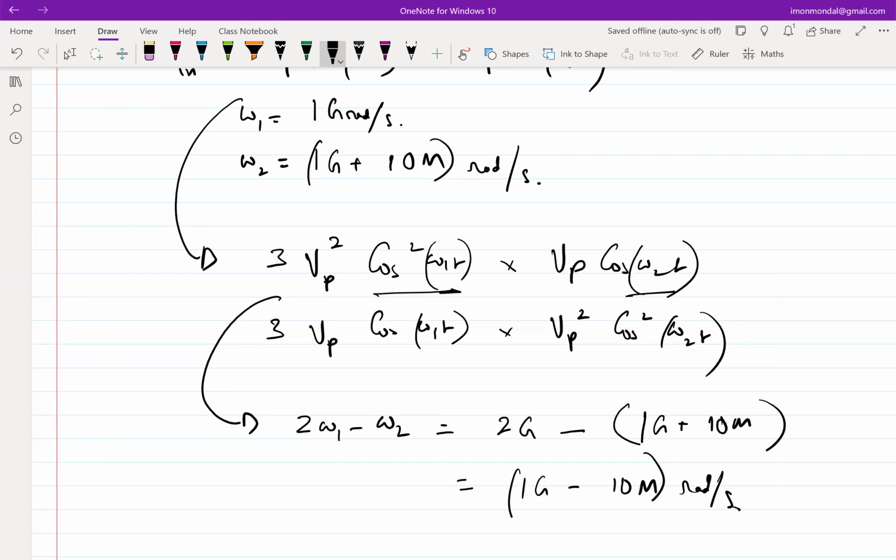But if your bandwidth of interest is only very narrow, you cannot do that. Right? You have to find different ways of characterizing your system. And in RF, that's why we have these metrics where you apply multiple tones close by and then see what folds back within your band of interest.